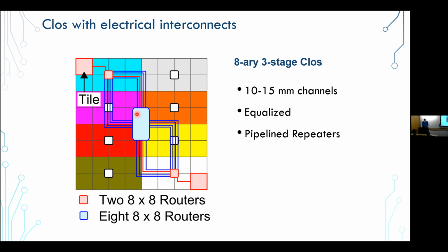Another strategy is to put things here in the middle. This way, all of your routes are basically the same. All the routes are essentially half of one edge of the chip, which is 4 times better than the worst case of the previous floor plan. The previous floor plan has the advantage that some wires are very short, from one group to another, but the longest one is really what hurts you.